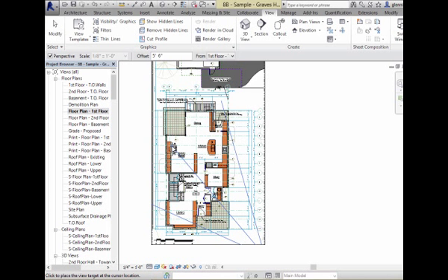And there it is. Notice as I'm placing it, I have this notion, it's the offset. That is how high I am off of the floor. So my eyes are about 5'6" off the floor. From the first floor, we can position that a little bit differently. If you want to be down here and look up, which gives you a more dramatic view, lower it down to 3, or be up and looking down. You have a lot of options here. Just place that camera.